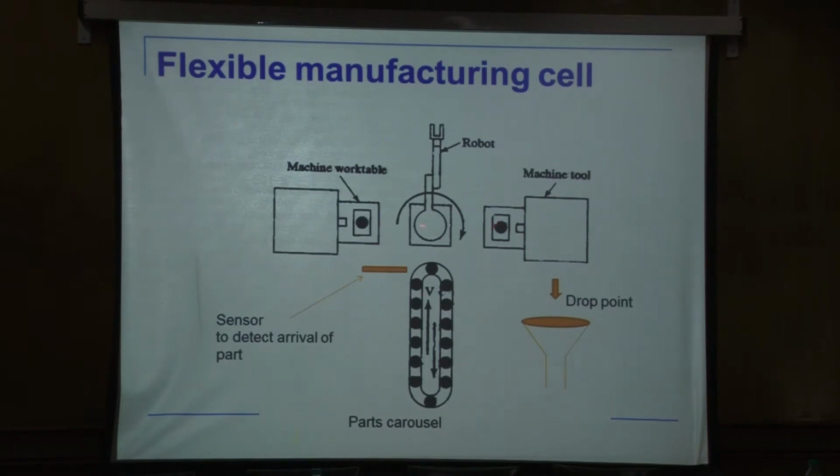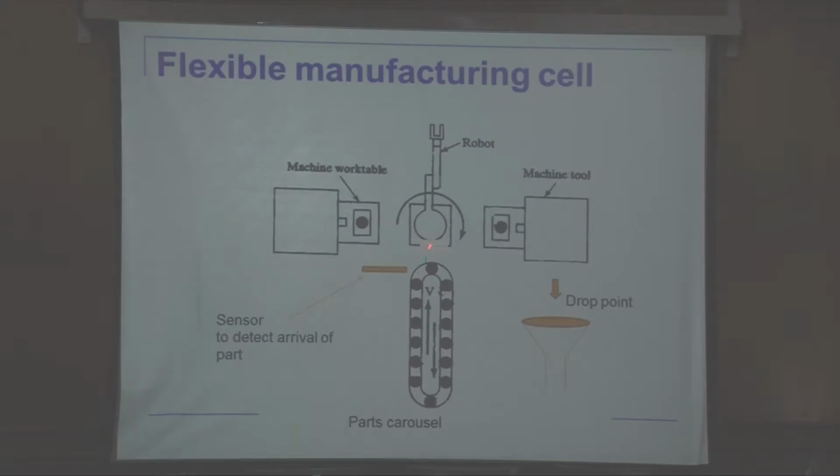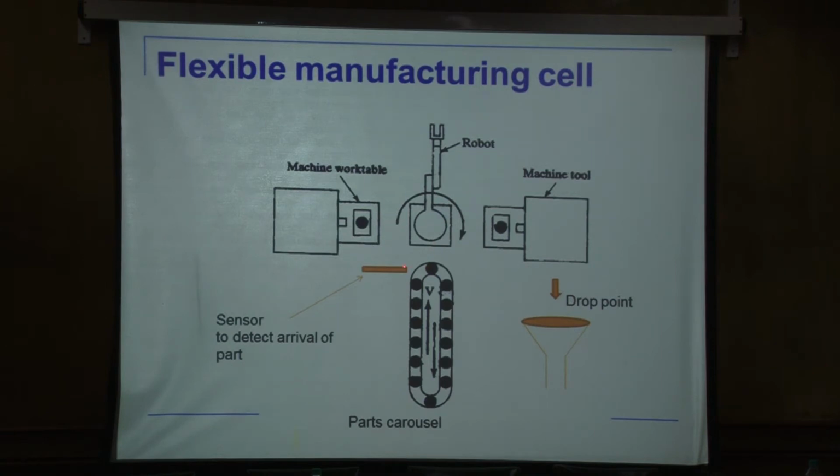Now in this, there is a sequence of operation, plus there are times of machining. Okay. So we have to sequence those times now. Otherwise what will happen is they will end up with a deadlock. So if this is doing machining, that is doing machining, and the robot also picks up one part from here, now it has no way it can pick that up and pick that up also. Okay. So when there is multiple machines, multiple times involved, then it becomes difficult to sequence.